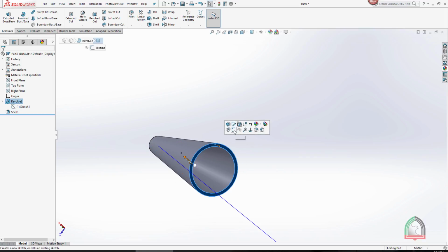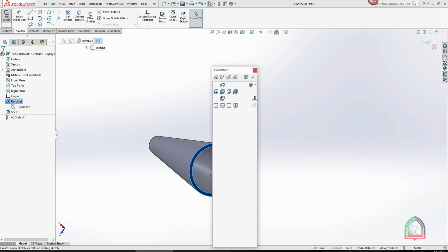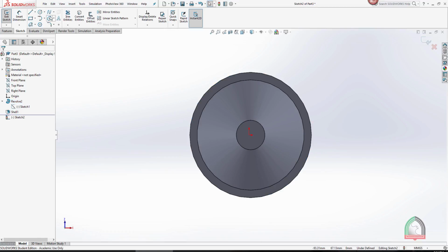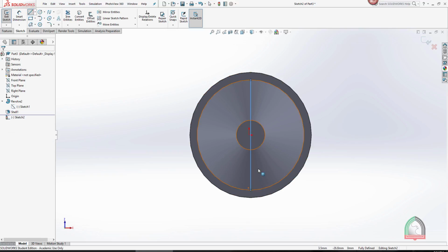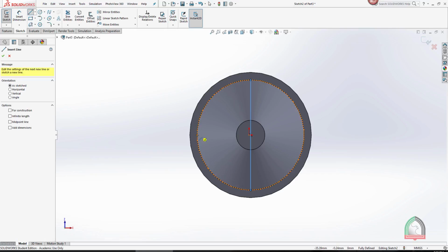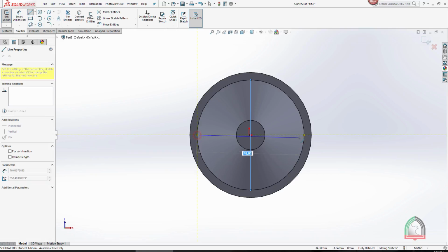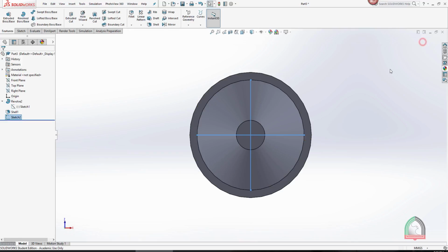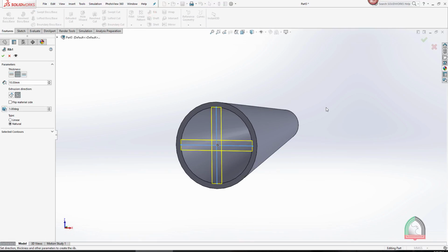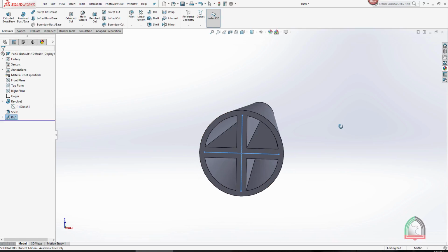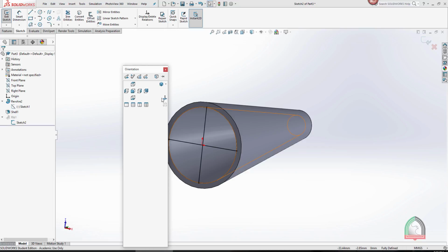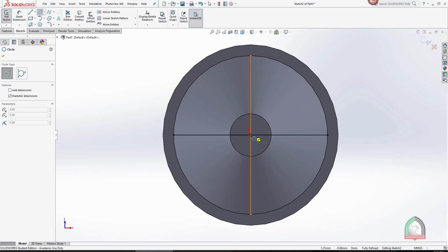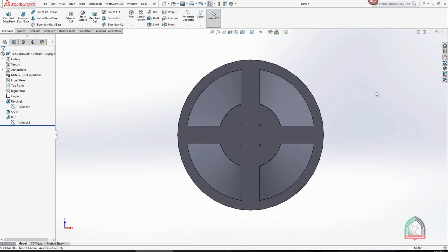But when we are using this one, here you can see that I'm selecting the face, making it horizontal, normal, and I'm joining from here to here, and also from here. Now exiting the sketch. Go for the rib option, the other side here. See, it will be distributed automatically over the surface. If you want to make any change in the rib, here I am deleting this and I am making a circle in the middle and exiting the sketch. It will come like that.